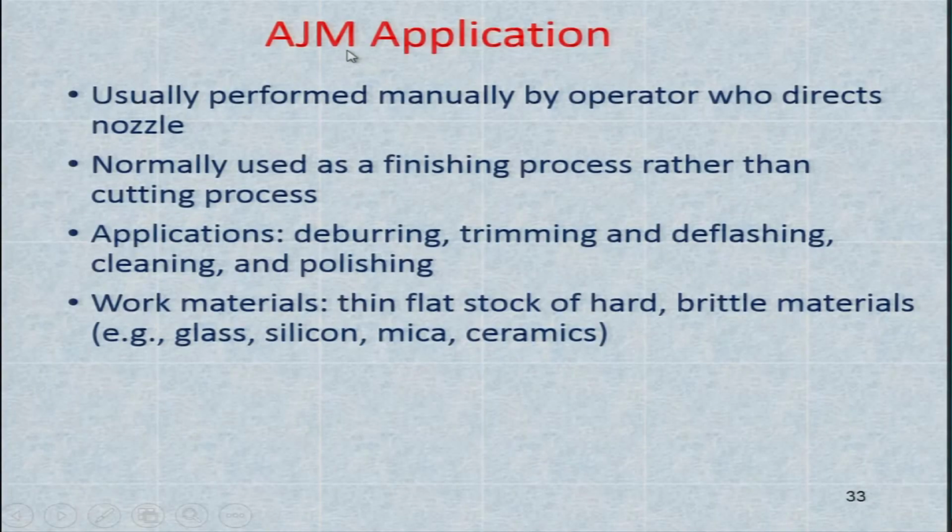Application where the abrasive jet machining process is applied, usually performed manually by an operator who directs the nozzle and traverses it manually. It is normally used as a finishing process rather than a cutting process. Mostly, as I said, it is water jet machining that is popularly used for cutting, but abrasive jet machining is used more for finishing operations, so that the ultimate surface roughness can be obtained.